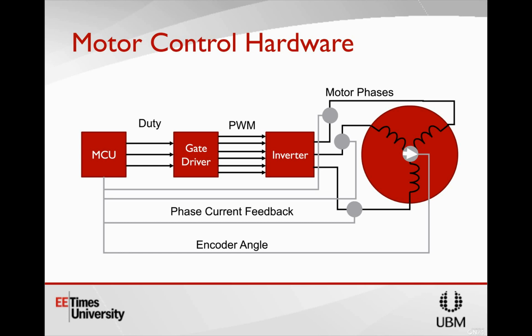Now obviously you can buy better and better encoder hardware, which will improve your robustness, but at that point it's also additional cost. And if you can do a sensorless algorithm based on the motor phase currents, which you're already measuring anyway, that adds a lot of robustness into your system.